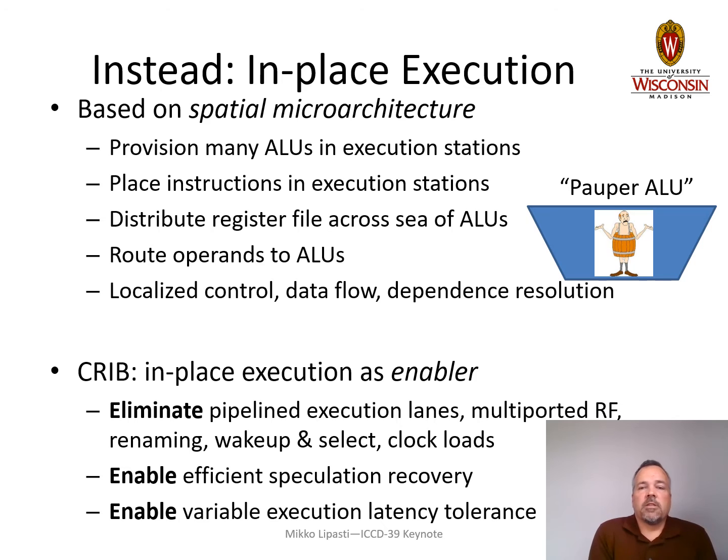We designed such a system, and we found that not only was it effective at reducing power, it was also useful as an enabler. It enabled us to do a bunch of things that previously were either difficult or impossible to do. So we eliminated pipelined execution lanes. We completely got rid of multi-ported register files. There isn't anything that looks like a register file anywhere in this design. We don't need register renaming in the classical sense. We don't need any scheduling logic that does wakeup or select. We have very, very few clock loads anywhere because we have very few clocked elements in the design overall.